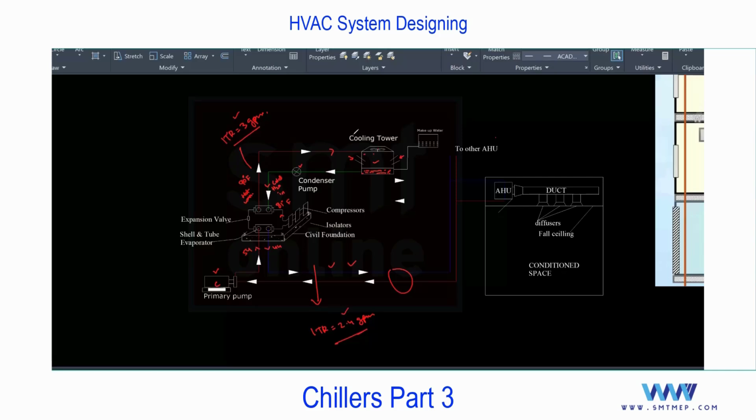No? So what will happen? The level of water will decrease. So we require a make-up water tank or a supply from the plumbing with a float valve. Suppose I'm supplying from the municipal supply at the lower level, anyhow a float valve is required. With the float valve, once the tank reaches the water level, it will close. Anyhow, the detail we'll discuss later. So we require make-up water also to maintain the water level. It means compared with the air cooled, the water cooled chiller requires a continuous supply of water, right? And in case of scarcity of water, we cannot use this water cooled chiller. This is one difference. We have other points also to discuss.